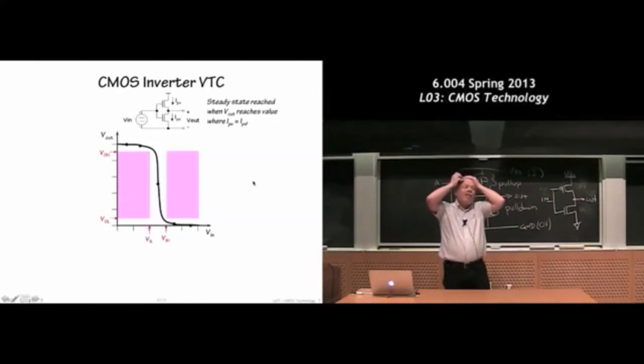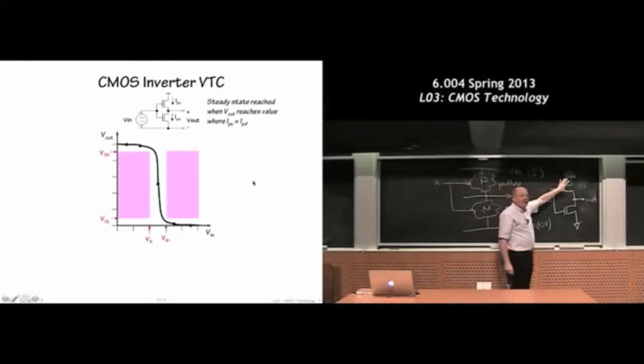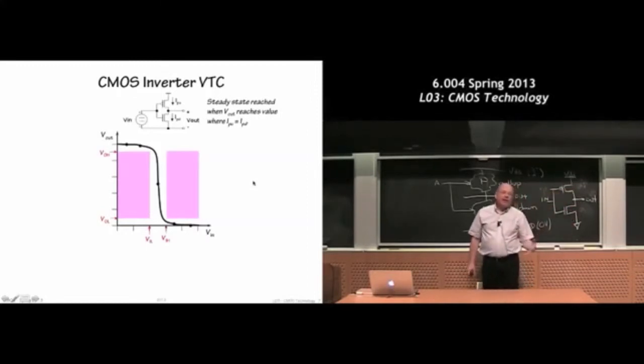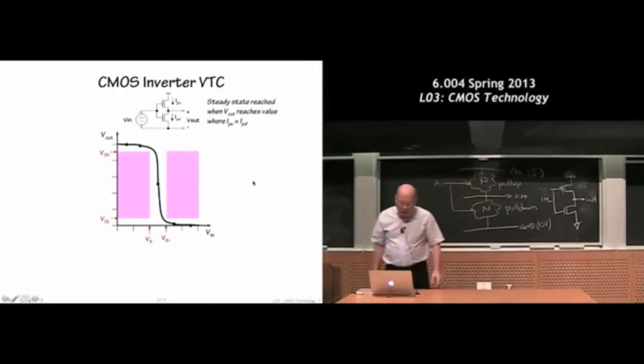Well, that they're never both on at the same time. That would be a real disaster. Or if they're on at the same time, they're only on for very, very small fractions of a second, you know, a picosecond or two. So when I design these networks, I'm going to have to design them to be complementary. In other words, if one is on, the other is off, and vice versa. So that's the whole story behind complementary logic.